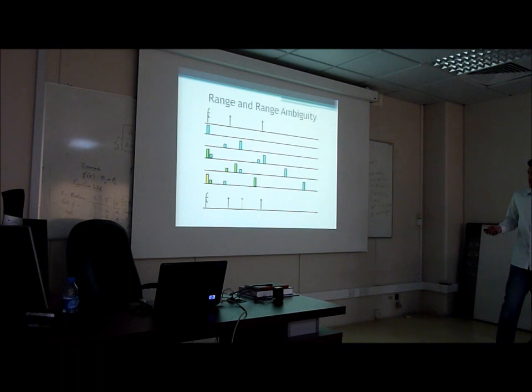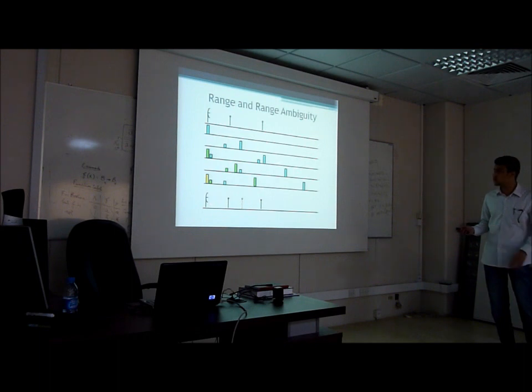But while transmitting this pulse, the first one is still going through the airspace and will have another return from the other target. So we have this return for the first one, and this is coming back to the radar. While the green one is transmitting, it will also get a return from the first target again. So at the end, you'll have this one returning to here and this returning to here. The green one will return before the second target's return from the first pulse. So we will have this one here as this target, and then when the green one comes to the receiver, we see it as if there is a target here from the first target. Well, we expect that there isn't any target there. And then when the other one comes, we'll see the other target. So in fact, we'll see three targets instead of two. This is what we call range ambiguity or uncertainty.